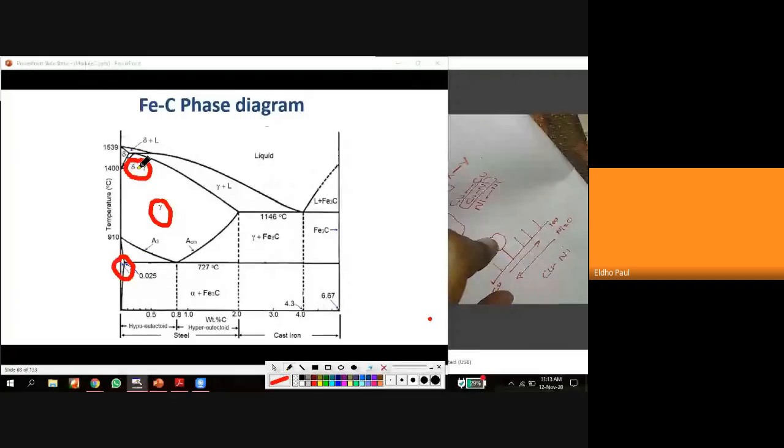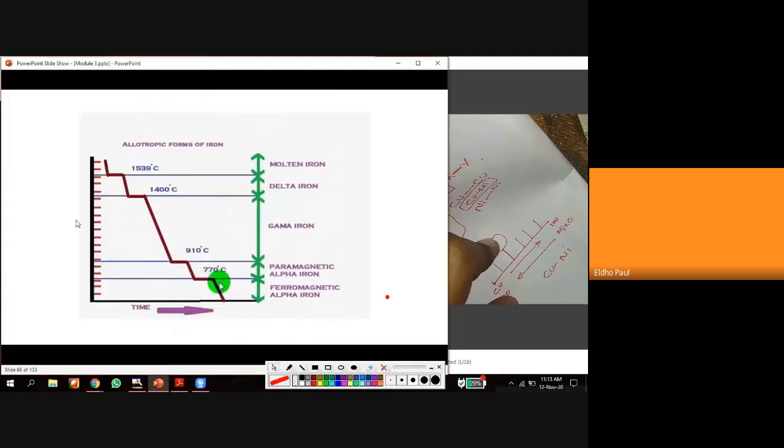And here we can see an intermetallic region. So in case of this Fe-C, that means the iron carbon equilibrium diagram, we can see everything. A single solid solution is formed at a particular composition, a multi-phase solid solution is formed at a particular composition, and an intermetallic compound is also formed at a particular composition of iron and carbon. Okay, so that is the third case.